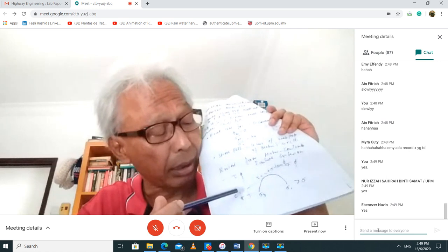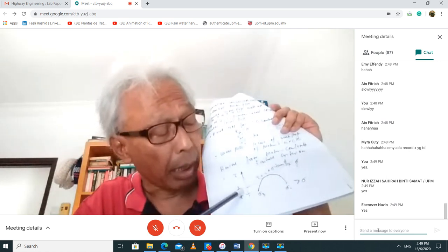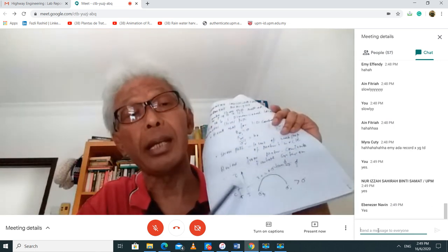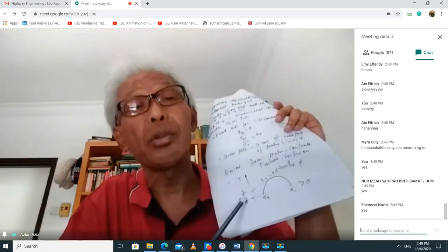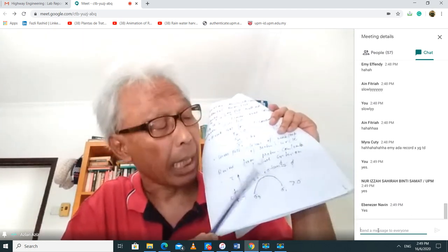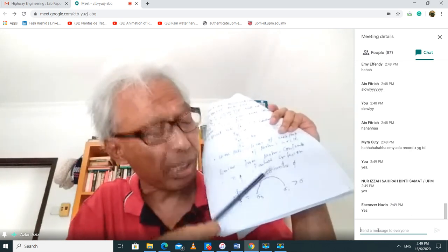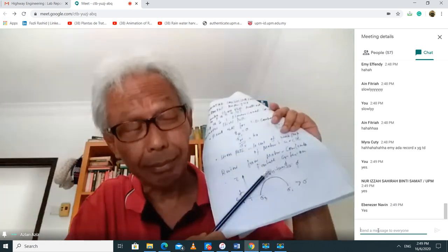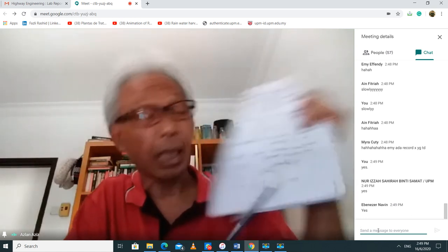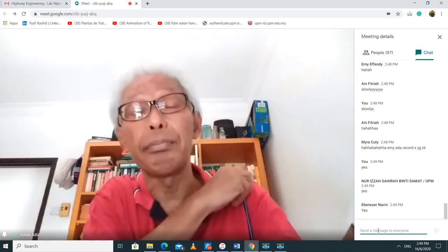And this line that is tangential to the Mohr circle intersects the vertical axis at the cohesion you call C. This parameter you call C, cohesion. And this straight line, which is tangential to the Mohr circle, you can reflect through this formula. That formula says tau equals C plus sigma tangent phi.